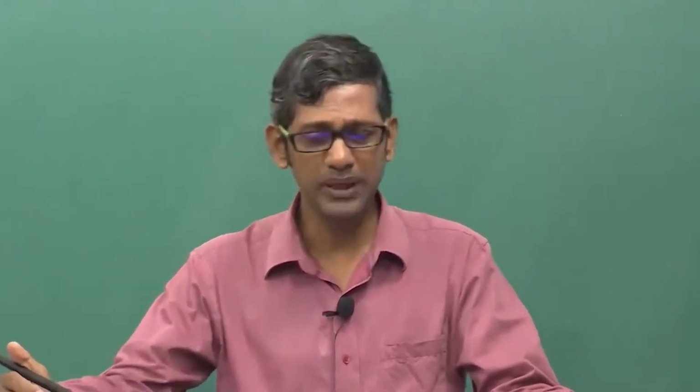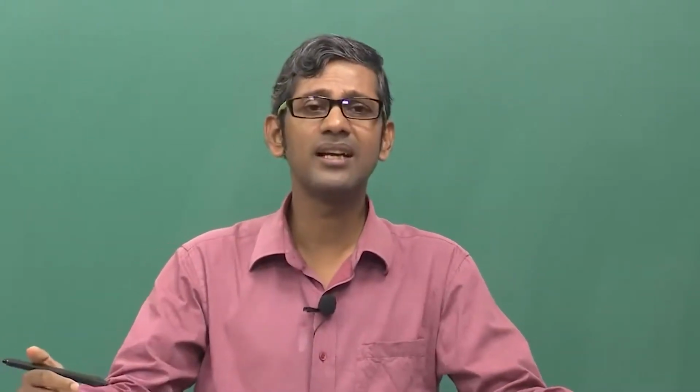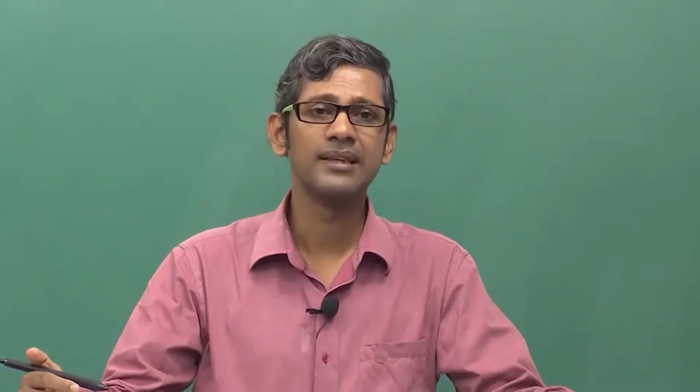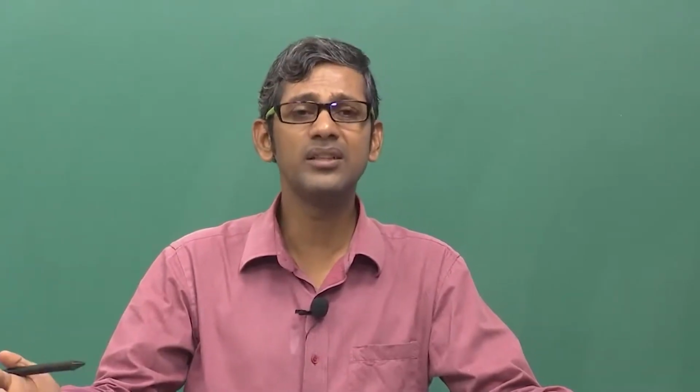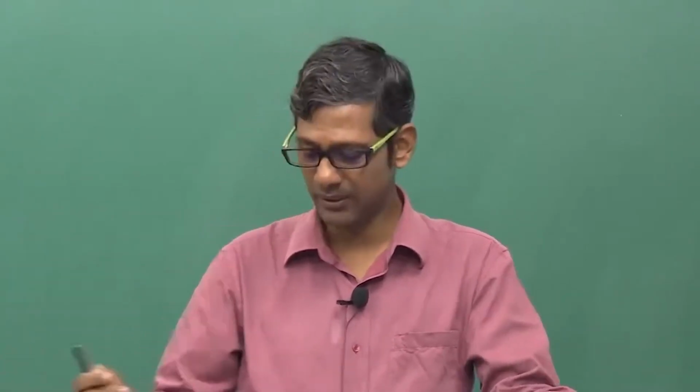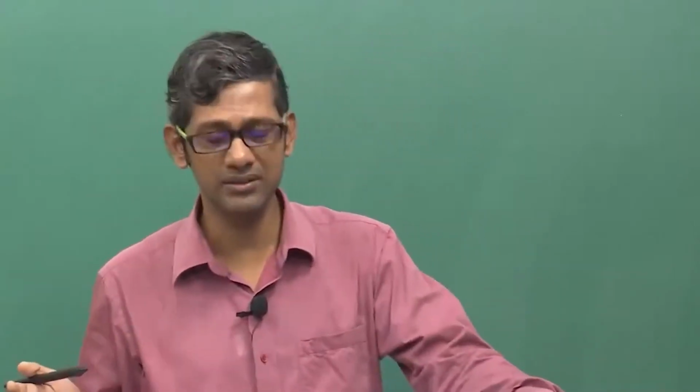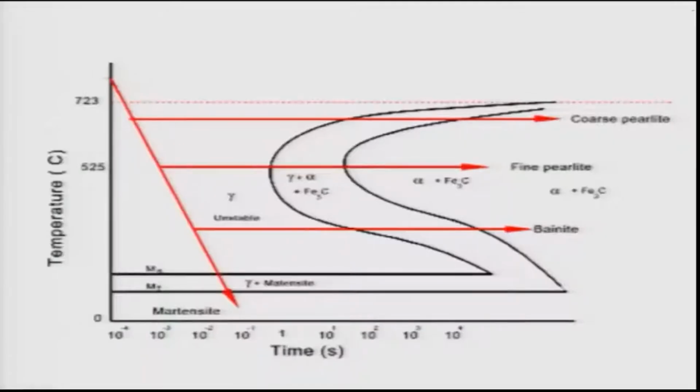Normally, plain carbon steel like 1080 steel has a large critical cooling rate, and that is why, to decrease the critical cooling rate, alloying is done. Remember, alloying means putting in different alloying elements like manganese. Manganese leads to shifting of the nose to the right side. That is what is shown here. The nose of this C curve has been shifted extensively to the right side. So the critical cooling rate, which is given by this line, this is CCR, is much lower.